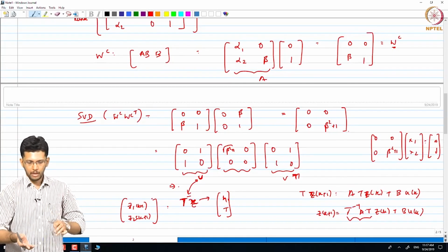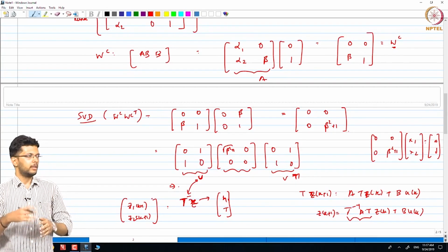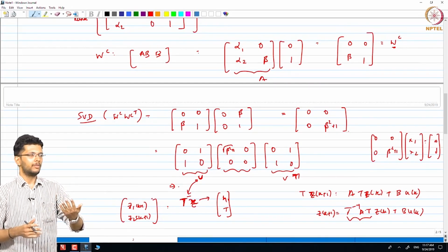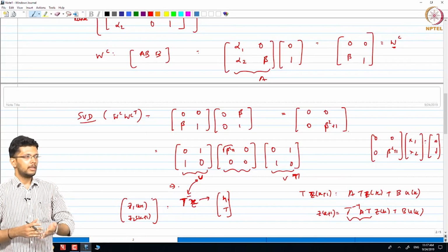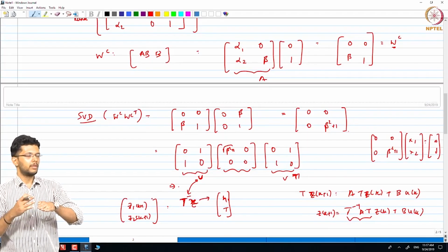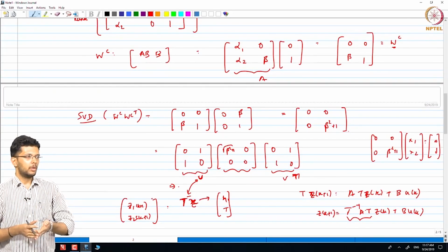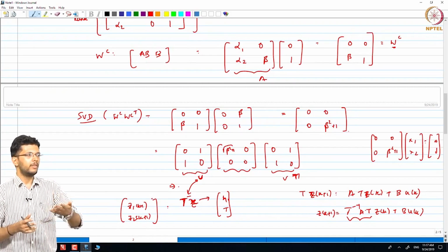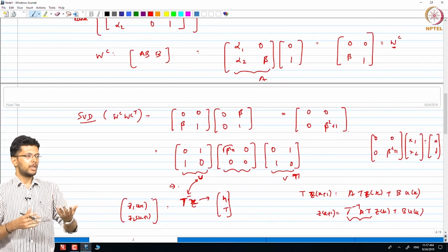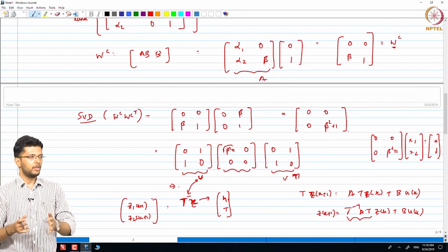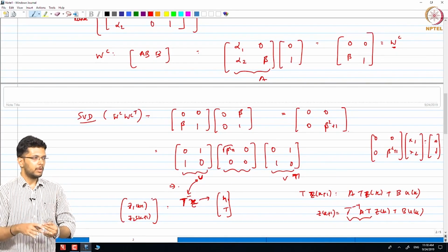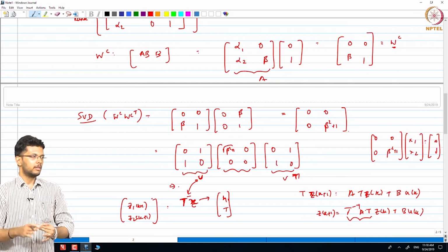Say your heater load is at most 100 kilojoules per minute, and you want to reach a temperature of say 400 or 450 Kelvin. Since there is a restriction on the maximum heat duty of 100 kilojoules per minute, let us assume the system will reach only say 350 Kelvin. If you want to reach 400 Kelvin, that is not possible. So this concept of controllability and reachability is applicable for an unconstrained case.